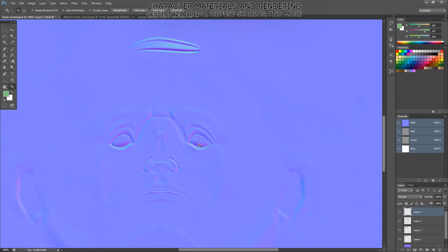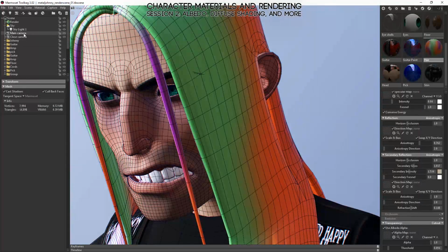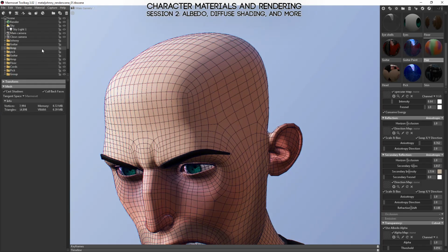For example, if you have a normal map that is specifically made for, say, the Unreal Engine, and it uses a specific algorithm for determining the direction of normals and such, saving it as a JPEG will throw away some of that information, which will make it so that in the engine it doesn't just look like it's a little bit compressed and has those little squares like we saw on this guy's head, but it will also make it pretty much unusable under most circumstances because it's never going to light correctly.